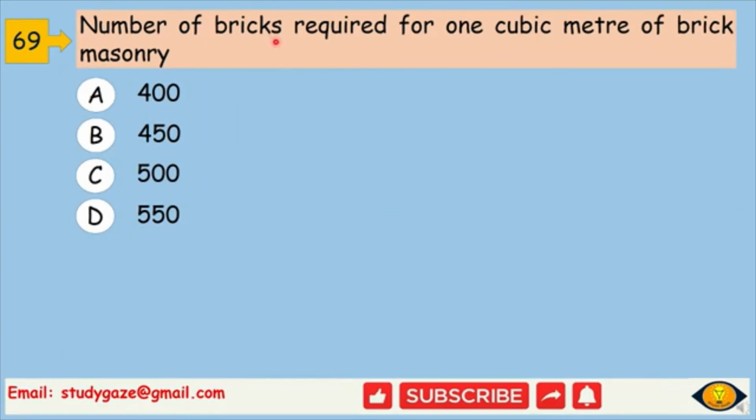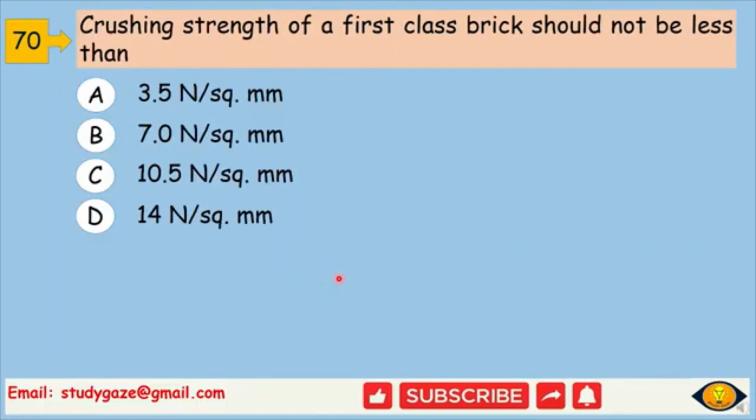69. Number of bricks required for 1 cubic meter of brick masonry: 400, 450, 500, 550. Answer is C. 500. 70. Crushing strength of a brick first class type should not be less than 3.5 Newton per square mm, 7 Newton per square mm, 10.5 Newton per square mm, 14 Newton per square mm. Answer is C. 10.5 Newton per square mm.